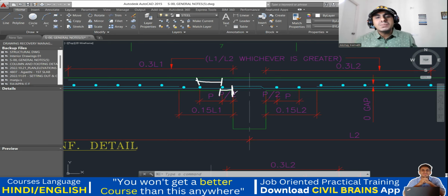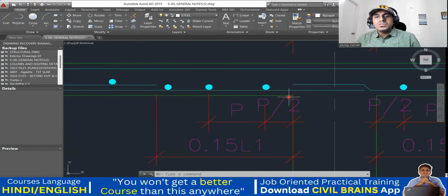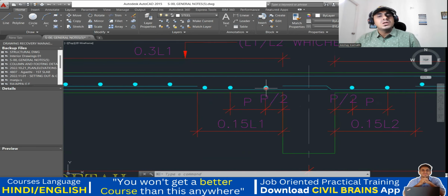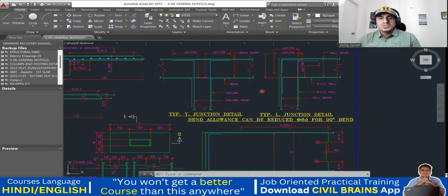In that case, you leave a gap of 62 and you can place your first rebar here. If you want, you can follow, but usually most of us don't follow. What we do is, wherever we have stopped, from there we leave a cover of 25 mm and then we start placing the first bar. But you can follow this also. Nothing much technical in that.